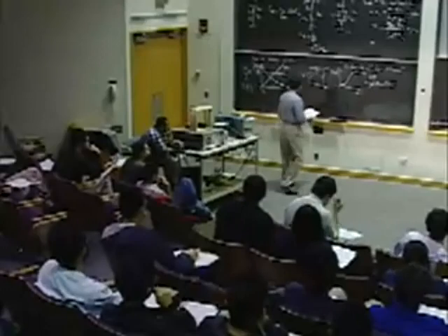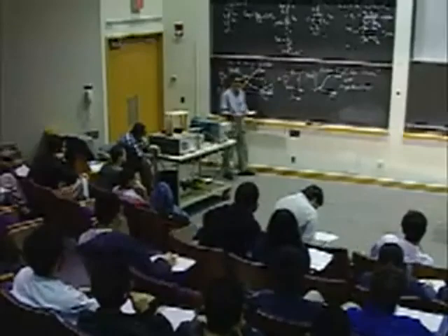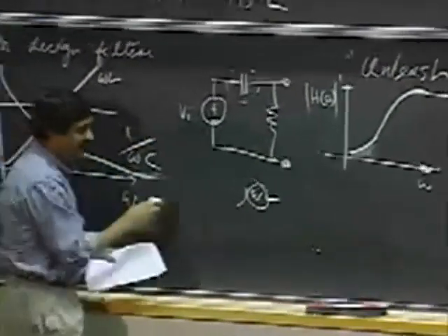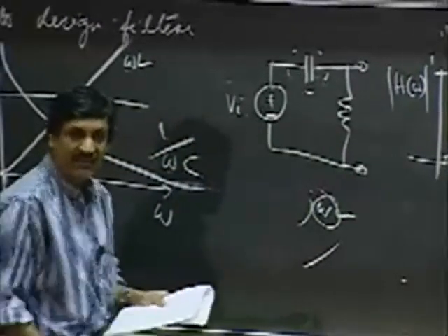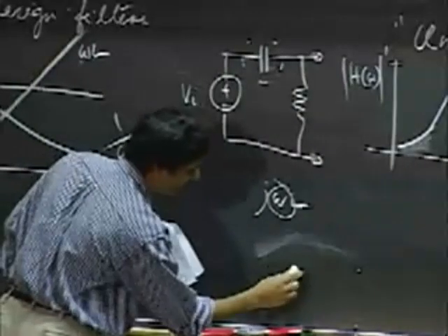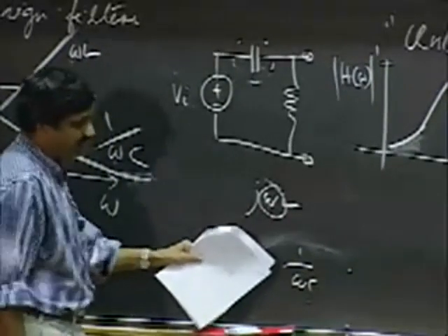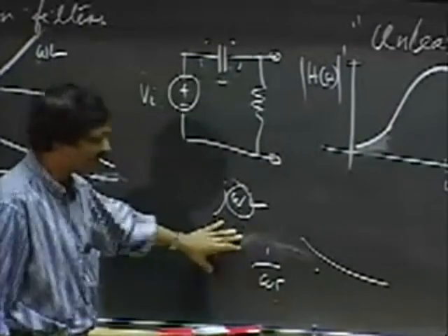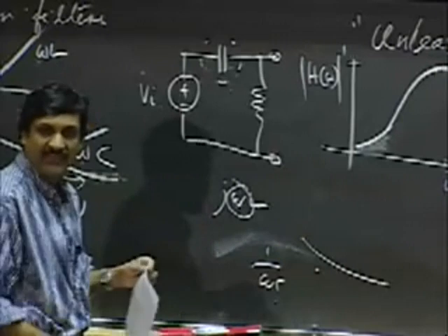Okay. So in the case of, if you get something like j omega L, what you can do is take the limit as omega goes to 0. And if it's omega L, then notice that it's going to start linear. Okay? And on the other hand, when you get very high frequencies, for example, if you get 1 by omega C, then this is a hyperbolic relationship, so it's going to look like this. So you can take a look at a lot of these functions at their very low values and see how they look at that point.